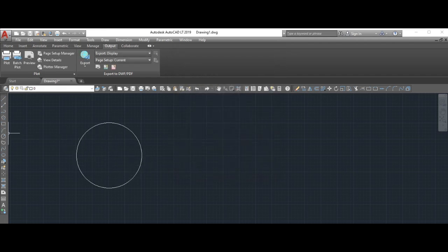Now I select this circle option again. I go to another point. Let's say I select this point here. I click, I draw. Now in between you see where it asks you for circle, so you type in 300. I want the second circle to be 300, so I press enter. So now we have drawn 2 circles. So we have learned how to use the circle tool.